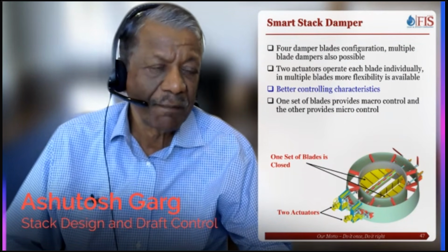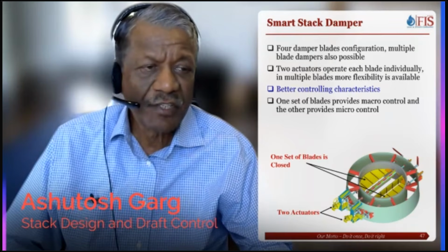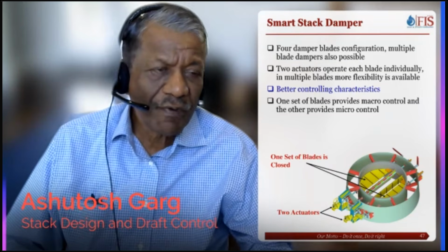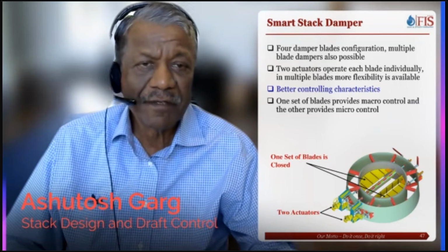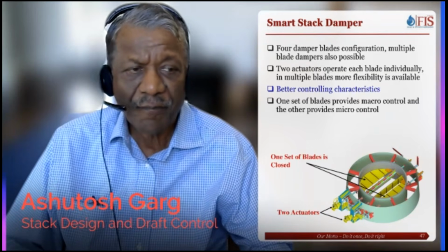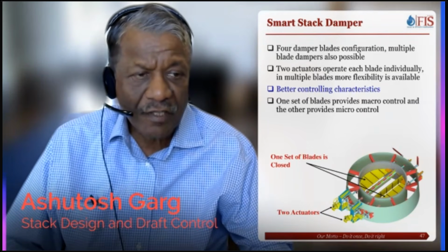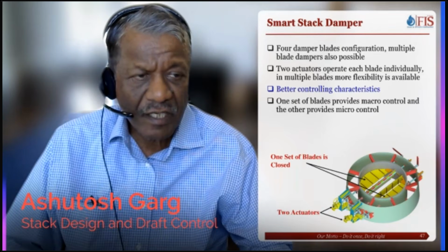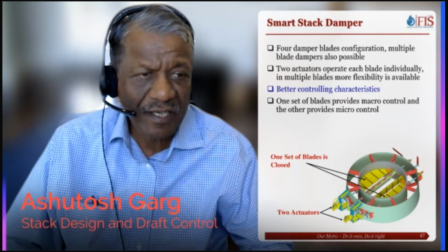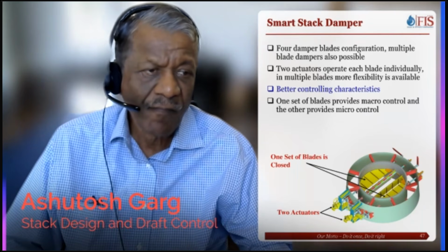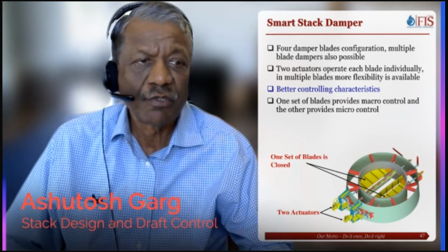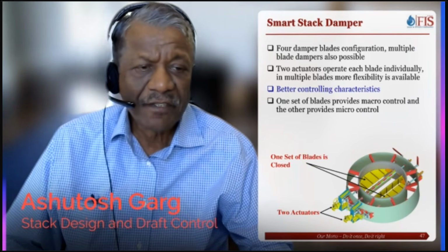We have supplied recently 3 units in Europe. We provide smart stack dampers as a standard equipment for all our new fired heaters. You can see this was a very unusual stack having an inner circle and an outer circle, and we put a 4-blade damper with 2 actuators to ensure that we can get the best control.